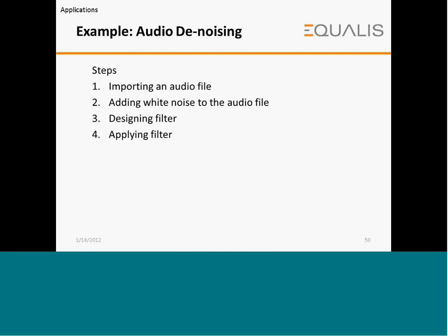Let's look at an example where these toolboxes are applied for signal processing. We have an audio denoising task, which is essentially done in 4 basic steps. We import an audio file, add white noise to the audio file, design a filter, and then apply the filter.